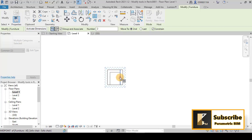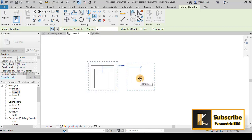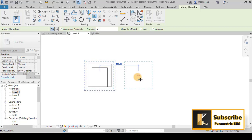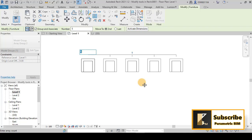You can choose the point that you want to array from to specify the distance between the seats. So I want to go by the center line, and now I want the distance between the center lines to be 1.5 meter. Then you can specify the number. For example, if I want to put 5, and then I will specify the distance, click, and this is ready.